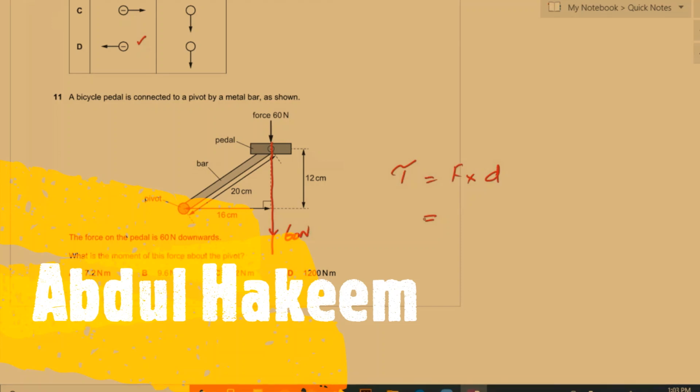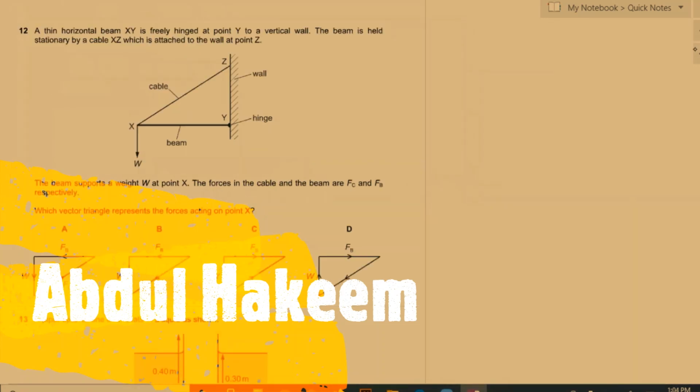So we will write force is 60 multiplied by its perpendicular distance from the pivot, 16 divided by 100. So the answer is 9.6, because this force is 60, and this is the perpendicular distance. So the answer is 9.6. Okay, move to the next.